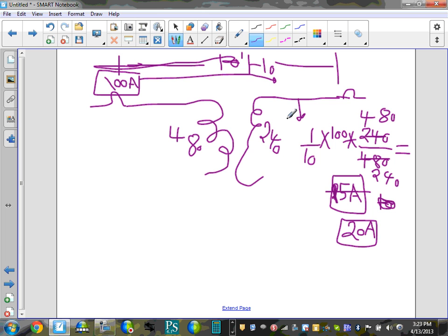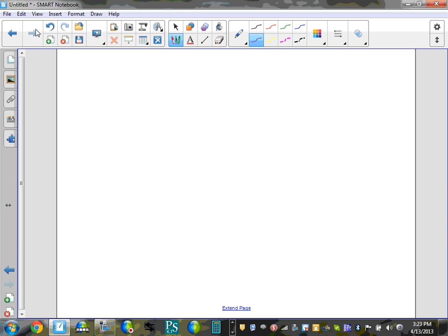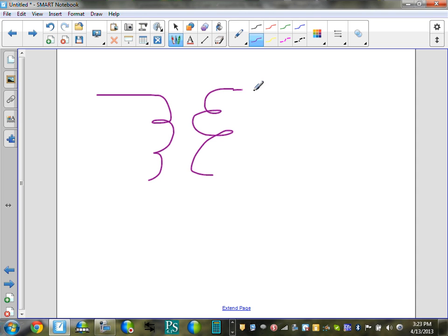Okay, so suppose that this transformer was 25 feet, so you're going to come over here. This time we're going to do it right. From here, my 25 feet and an overcurrent protection device. Let's do 100 amp here, the same thing, and I have a 25 feet secondary conductor from here to here. Cool. So the same thing, guys.